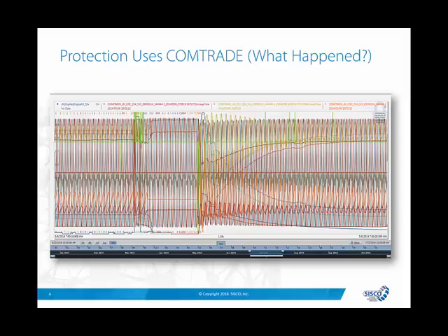In reality, the COMTRADE file creates a triggered digital oscilloscope capture of the pre-configured information that could be related to an event, which allows engineers to look at the data and determine what actually caused the event. Typically, the capture time frame is 3 cycles before the actual event and 7 cycles after the event was detected.